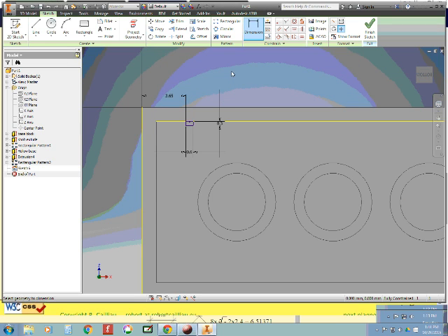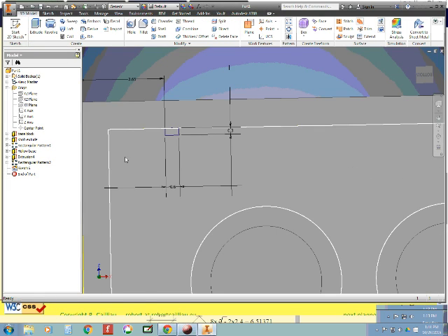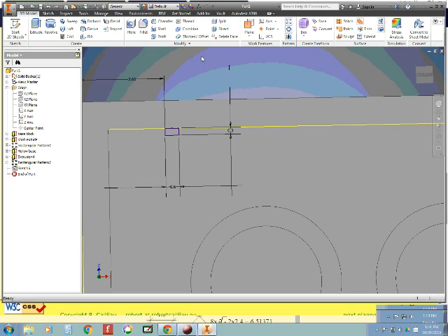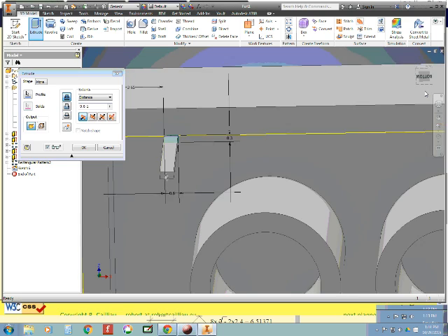Okay, so right-click and finish 2D sketch. And notice I didn't make these ones vertically yet because I think those have to be done separately. Okay, so finish the sketch. Again, now I want to extrude that. And there's my shape. And again, rotate. Look at where it's trying to extrude.